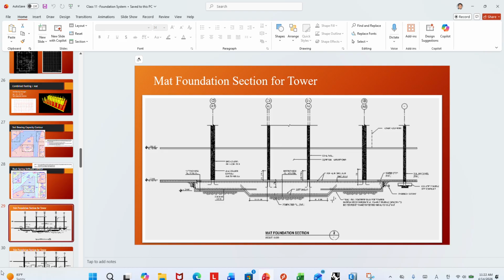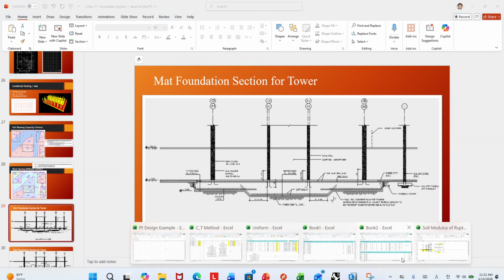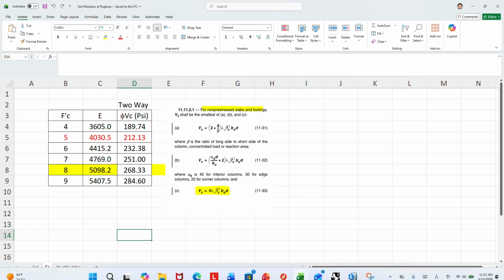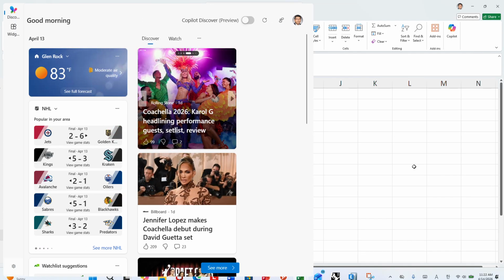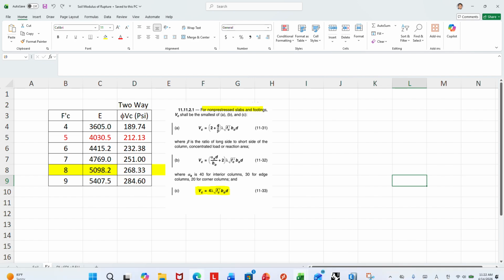That max-min value, the range of 212 pounds per square inch, is that going to be generalized for all of our designs? Is that the code? That's the maximum. Okay. Because I currently choose 5 KSI concrete for the mat. If we were to increase, if you are a designer, typically so far, I think 5,000 PSI concrete is pretty common for foundation design. Since high strength concrete is available, the premium is not that much.